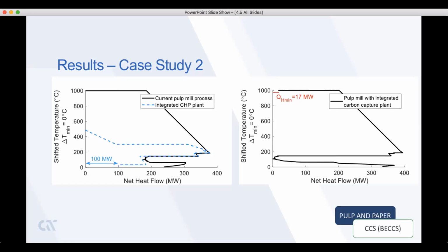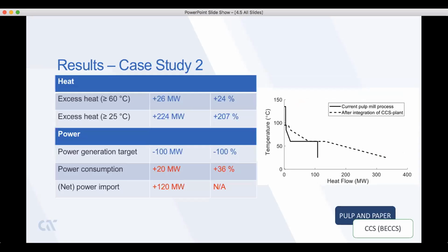According to the prioritization order, this work minimized fuel consumption was prioritized over cogeneration, meaning that there is no power generation in this scenario. This way, only a small heat demand must be covered by external fuels. Unavoidable excess heat is once again indicated by red circles here and will be highlighted on the next slide by the excess heat temperature signature.